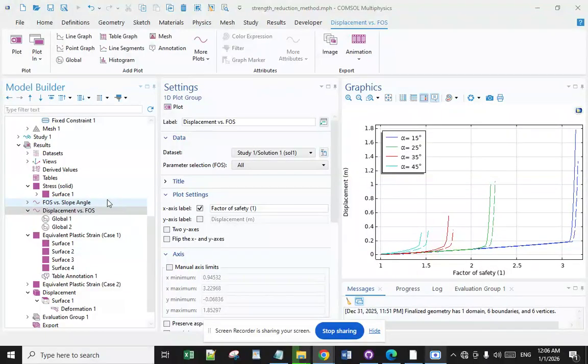Design factor and safety factor. The difference between the safety factor and design safety factor is as follows. The safety factor, or real stress, is how much the designed part actually will be able to withstand, the first usage from above. The design factor, or working stress, is what this item is required to be able to withstand, the second usage.